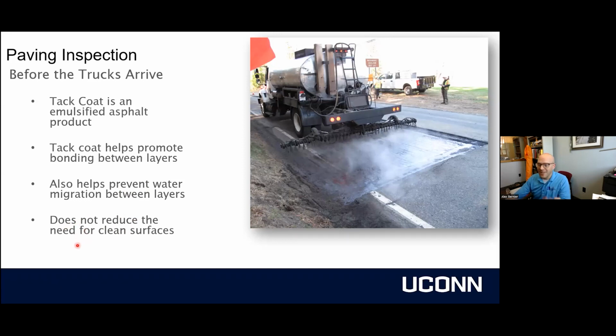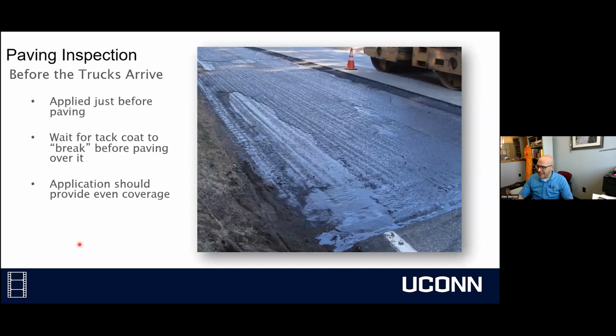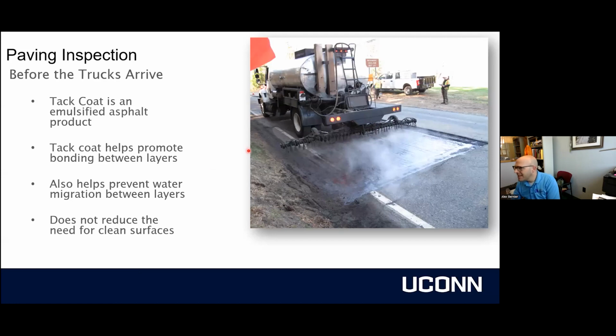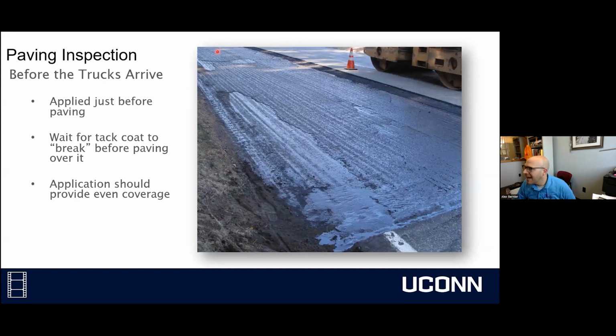If you want the dough to not stick, if you're making pizza dough or bread, you put flour on it. The dust in our road is that flour. And in our case, we want it to stick, so we don't want the dust. So similar concept, but opposites. Important to realize that. It needs to be uniformly distributed. So these nozzles here, you can see are triangular shaped spraying out. If they're dirty, they end up trickling like a hose that's left on. We want it to be a consistent amount of tack all across the mat.